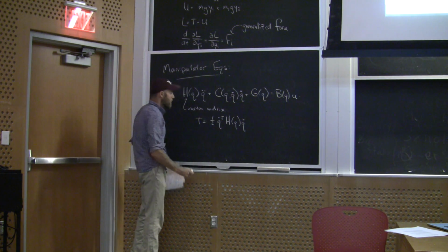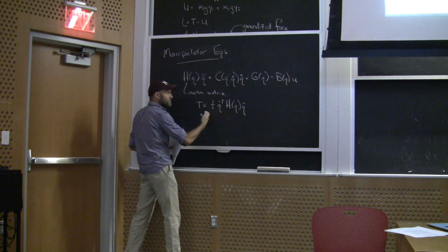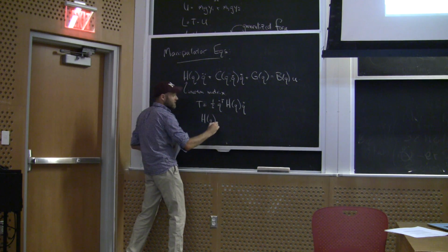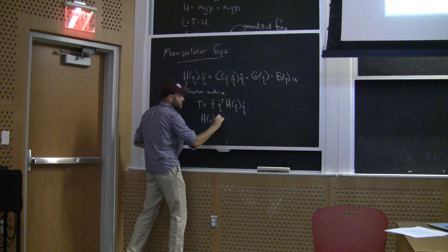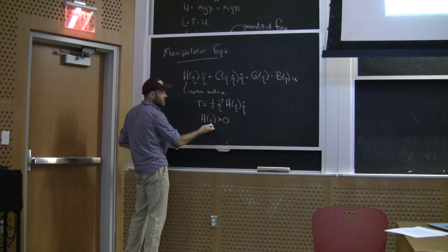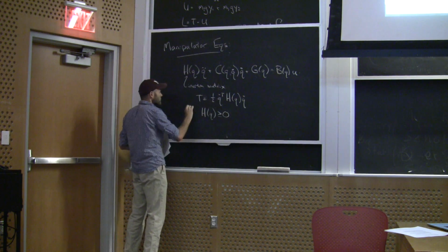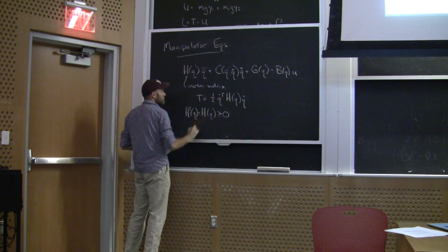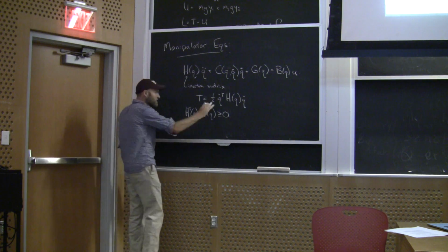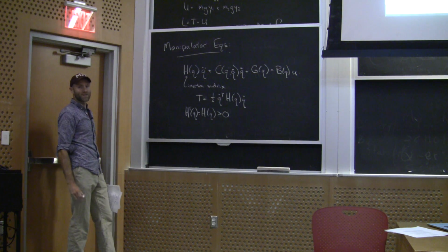That's important structure. And maybe by virtue of saying it's an energy, you can sort of believe that it has this important property that it's always greater than 0, okay? When I write a matrix greater than 0, I mean that it's a positive definite matrix. I'll be careful, I guess you could have a 0 mass system, but it also happens to be symmetric. For any reasonable system, it's strictly positive definite, because I'm going to invert it in a second, so I better make it strictly positive.